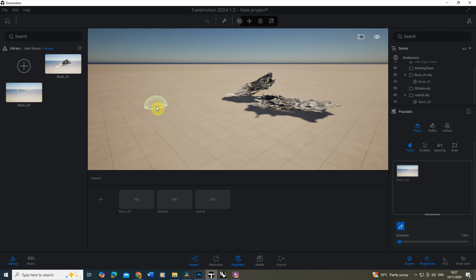If you do that, Twinmotion doesn't automatically downsize them for you, so if you start to scatter them, like I'm about to do here, it's going to be scattering tons and thousands of vertices of geometry in your scene, which is going to get really tricky to load, and if you do too much, it will crash the scene very quickly. So I'd always use this with caution.